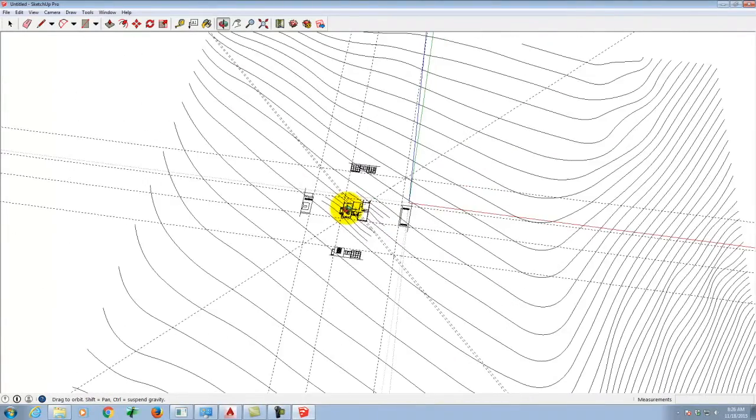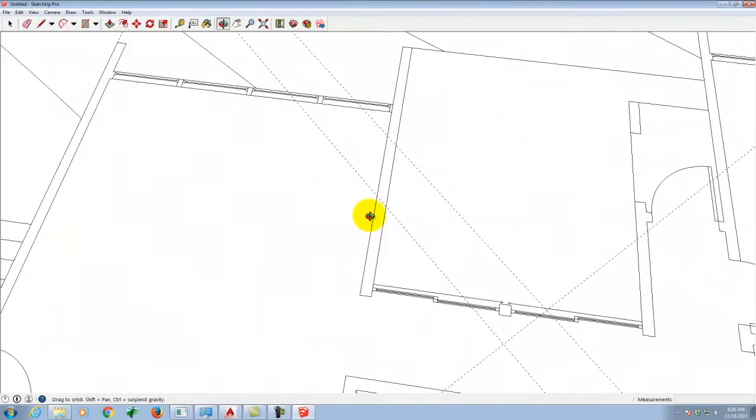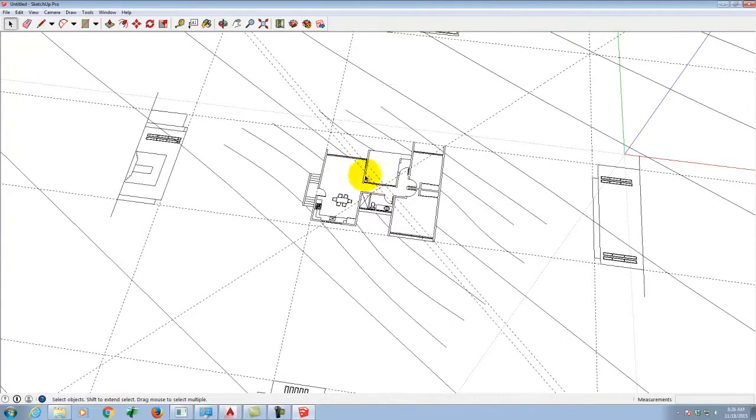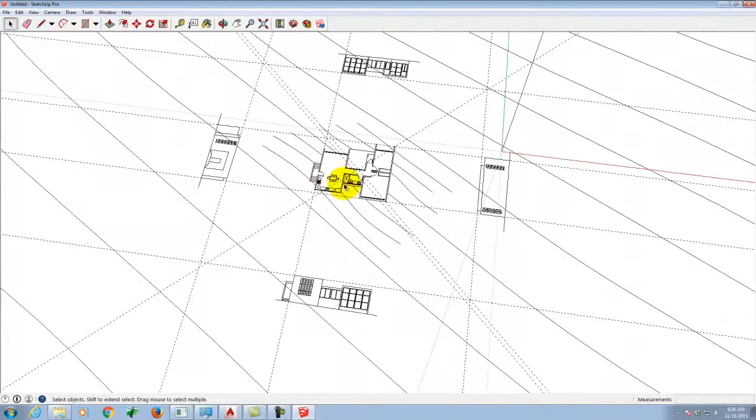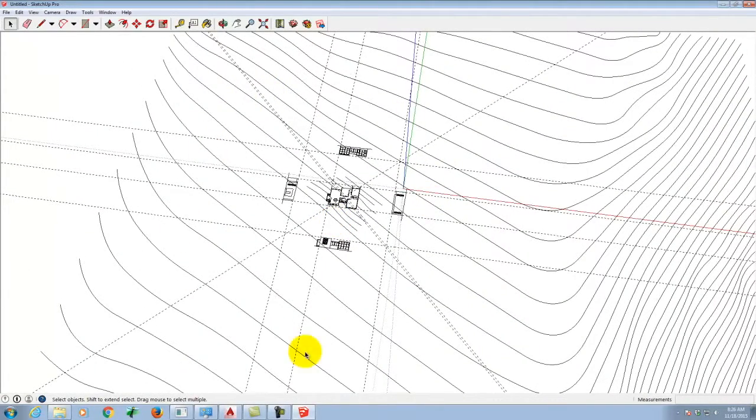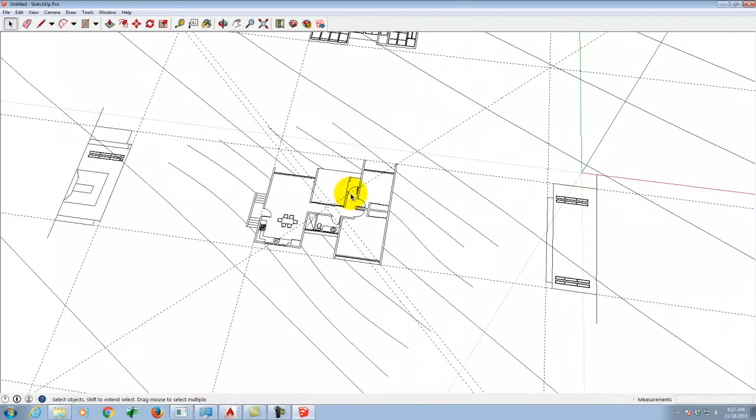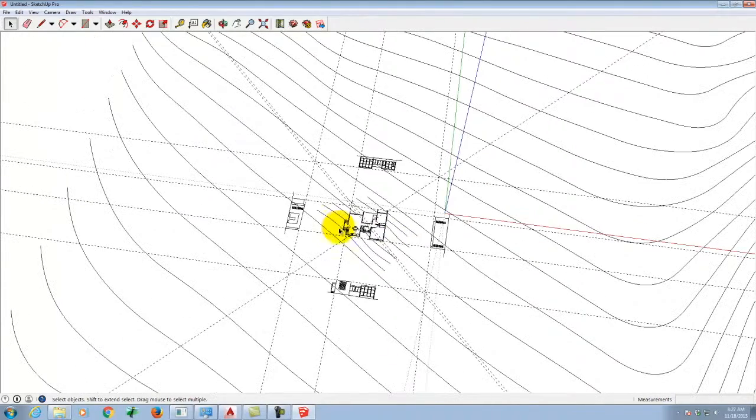OK, so I have this piece that came in as an AutoCAD drawing. It is a bunch of live lines, but in order to have good kind of reference points, what I'm going to do is I'm going to make this whole object a component such that it's not going to affect the geometry that it creates, but it's a good reference guide. I've done it where I've just used these as live lines. The problem is it gets really messy with the layers, and some stuff works and some stuff doesn't. It tends to be a little bit easier to just establish this stuff earlier on.